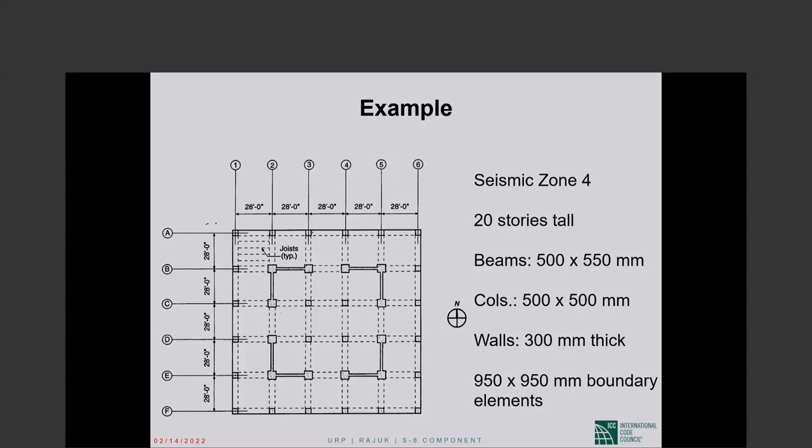If you have boundary elements as in this picture, I don't think you should have any problem developing the beam bars. If you don't have boundary elements, I can see that you have a relevant question, and I do not have an offhand answer. I have to think, or see if somebody like CRSI has a detail or something. I can't answer it offhand.